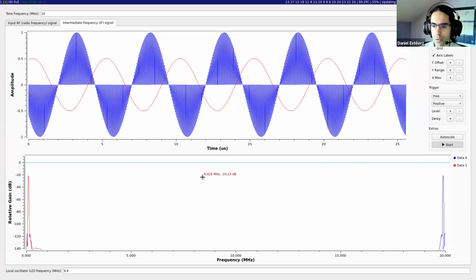What we want to do is to shift that complete FM signal, which is 300 kilohertz wide, to a low frequency, but the low frequency cannot be the audible range. The lower edge of the signal, we might bring it back down to some audible frequency, for example, 10 kilohertz, or even, 10 kilohertz is not audible, so 5 kilohertz.